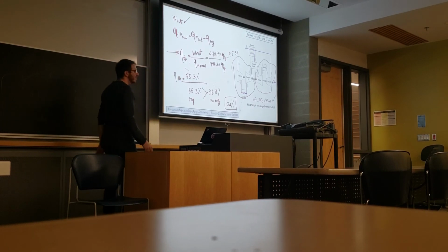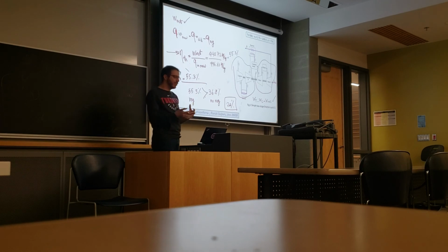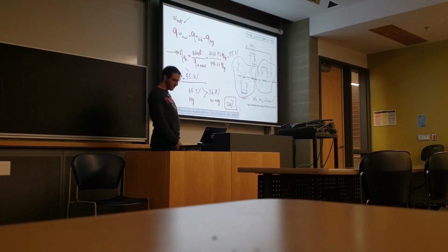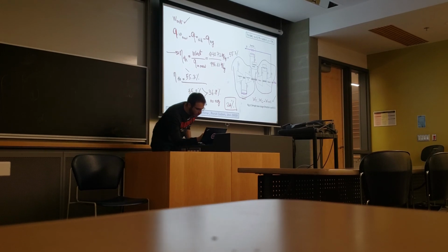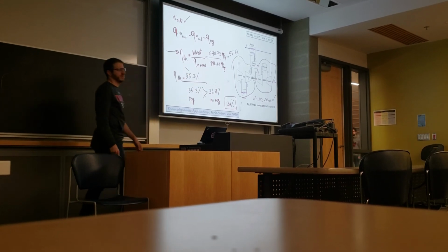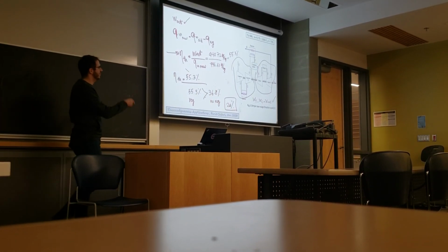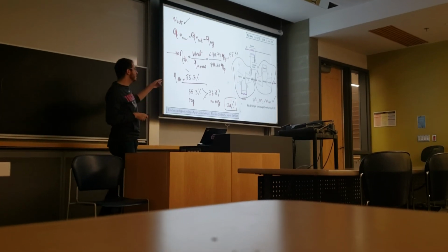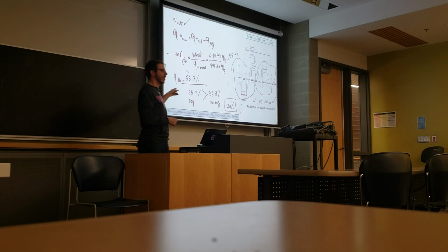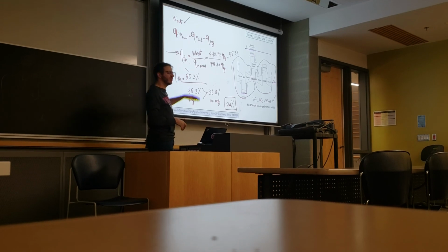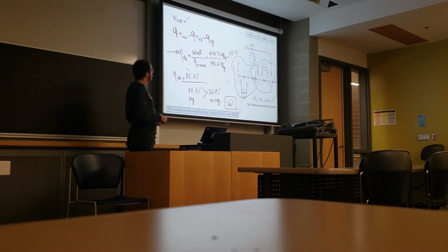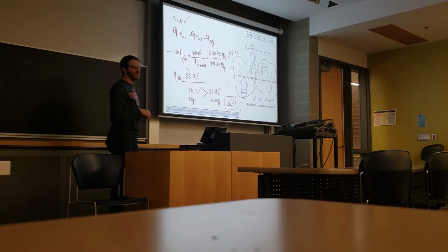Because we consume less fuel, the Q input lowers, and we have higher thermal efficiency. It won't go higher than 60% by any means of heat recovery and staging of turbines and compressors. So if you come up with 80% efficiency, it's wrong. With regeneration it's something between 40 and 60%, and usual cases are around 50%.